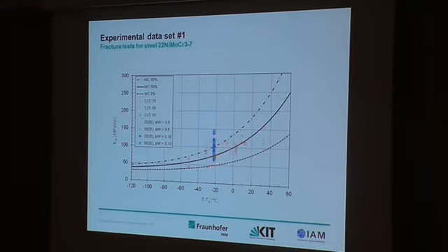Then you see here additionally blue points for shallow cracked SENB specimens. You know that this specimen geometry has a lower constraint, or in other words, slightly negative T-stress, and this brings these points to a beneficial position, so that they show high fracture toughness. And additionally, we put here results for the MT specimens, and they are distinctly outside the master curve scatter band. So we concentrate in the next slides on these specimens.